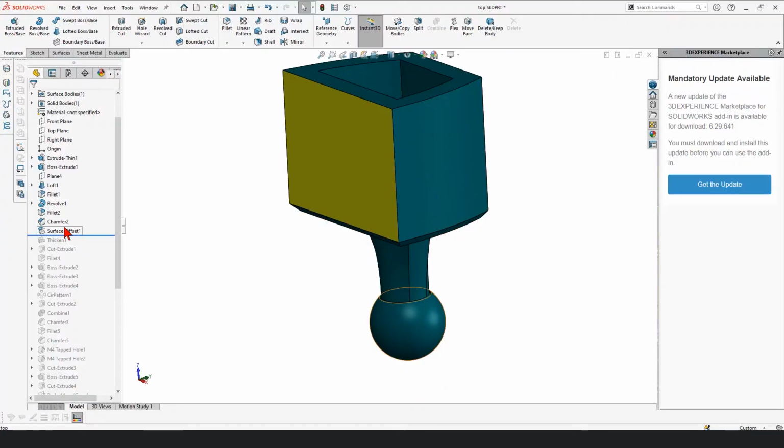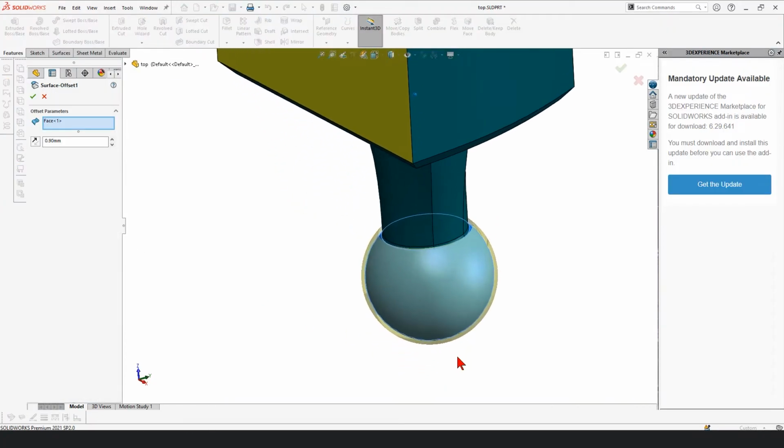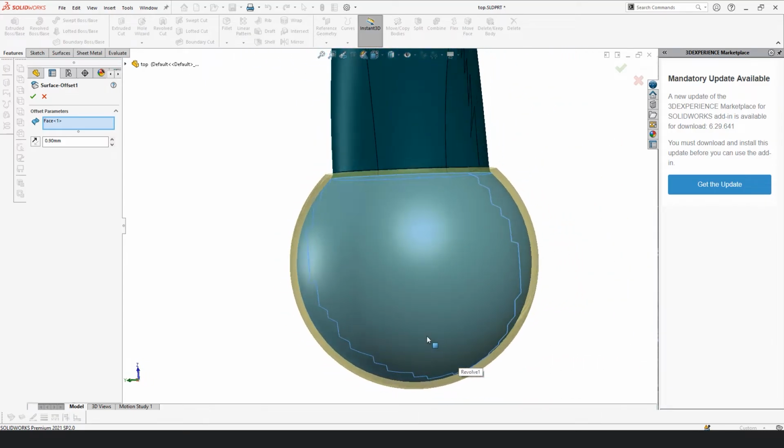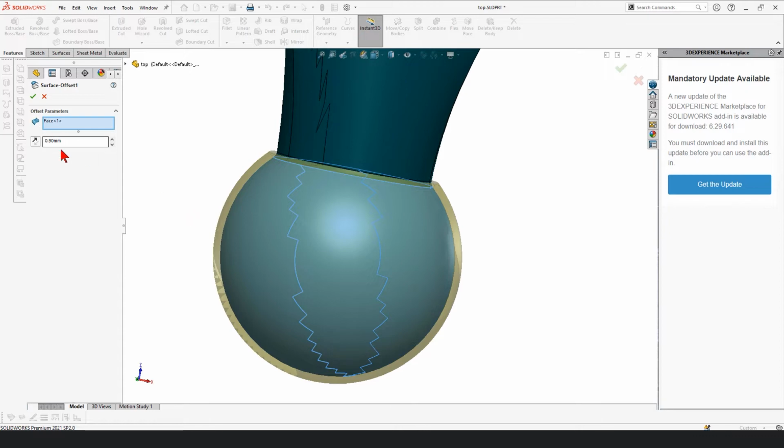So the first question that comes to my mind, what's the inner diameter of the joint? Or in other words, what would be the gap, the clearance gap between the ball and the joint, which is the pocket around the ball? Is 1 millimeter too much? Is 0.1 millimeter too small? Is it too tight to move? Then again, I don't know the manufacturing tolerance of the 3D printer I'm going to be using.